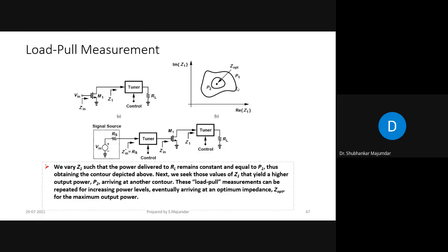Okay, so now while we are measuring the power amplifier, how do we measure? We are designing something, we have fabricated something, but how to measure? The basic measurement tool is load pull measurement. In this load pull measurement, we are putting in impedances in the imaginary and real parts, and then we plot the contour of the optimized impedance, which can be tuned.